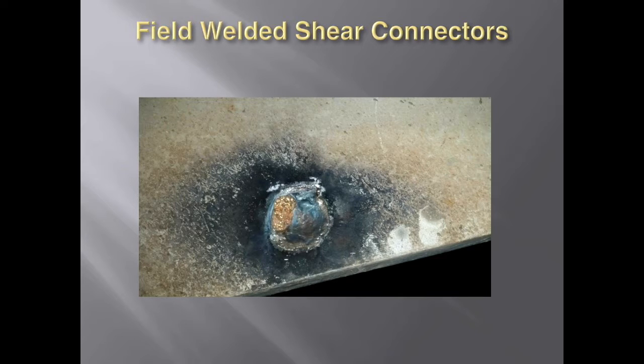They had gone through and welded a bunch of studs. This was an existing structure. After they got finished, they went to pull the ground off and noticed the ground was stuck to the bottom of the girder. And this is what it looked like. Basically the size of a quarter, and it went into that bottom flange about 3/8 of an inch, which for a welder, welding overhead's not easy, and to clean that out is even worse.